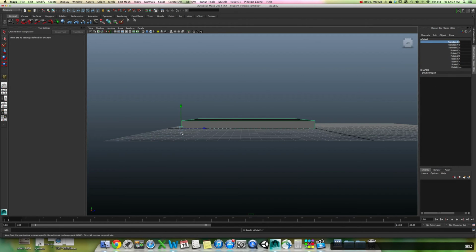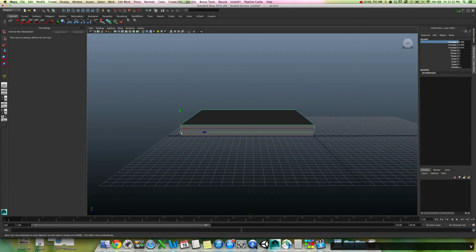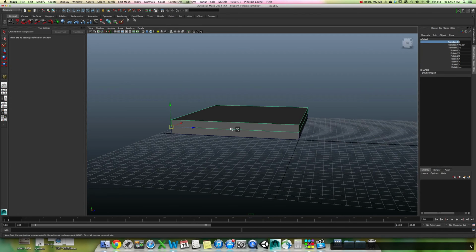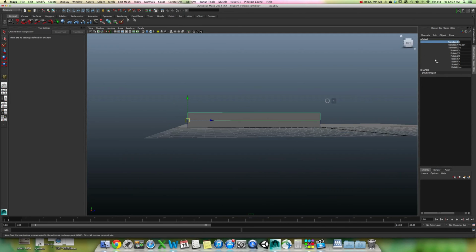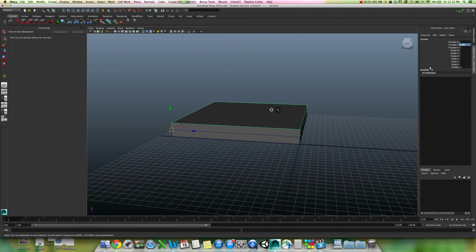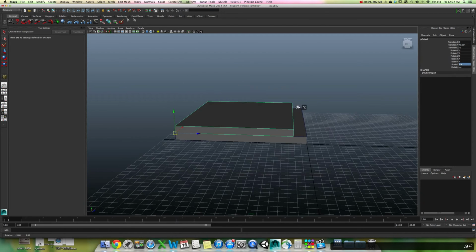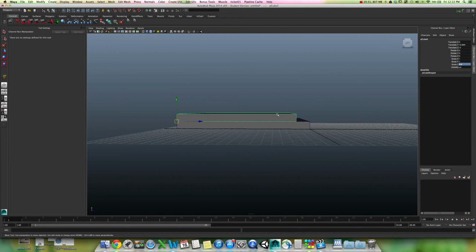Now, what I can do is just duplicate this here and hold my V key down. And we can see that the exact distance between this point and this point is whatever our offset in Y is. So now we have a really simple way to tell what's the offset, 12.904. I'm just going to copy that. And now I can change my scale of Z to 0.9, which will peel back the first layer of stairs.